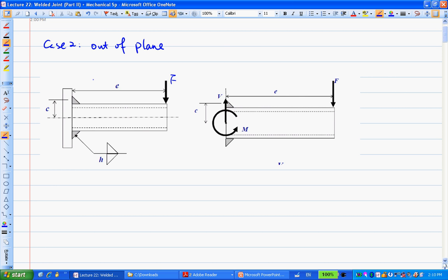understand. So basically, let's say you pick a point on the weld group. Now, where do we pick the point? If you remember in the previous lecture, when we analyzed welded joints, we used a conservative model, right? And that conservative model says we only look at the throat area. Basically, you only look at this area here. You can pick any point somewhere over here, just for illustration, but you need to understand that the point you picked is on the throat area here.